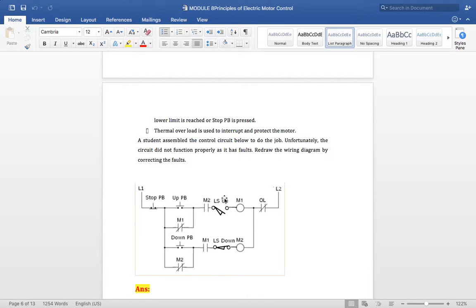So in this figure it's given opened. It should be normally closed like this, so that the elevator will move upwards, right? So when you press the up push button, this should be closed, and so the elevator should move up until the fifth floor is reached, then only it should be opened. This is the point. And you can see the relay coil here, this is right, but you can see an auxiliary contact here which is M2 and this is M1.